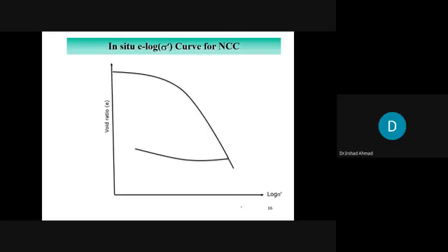First of all, you find the pre-consolidation pressure using Casagrande method, which you have just done. And then you found the sigma naught prime, and both are equal, so that is a normally consolidated clay. ठीक है ना? Now how to correct this curve?